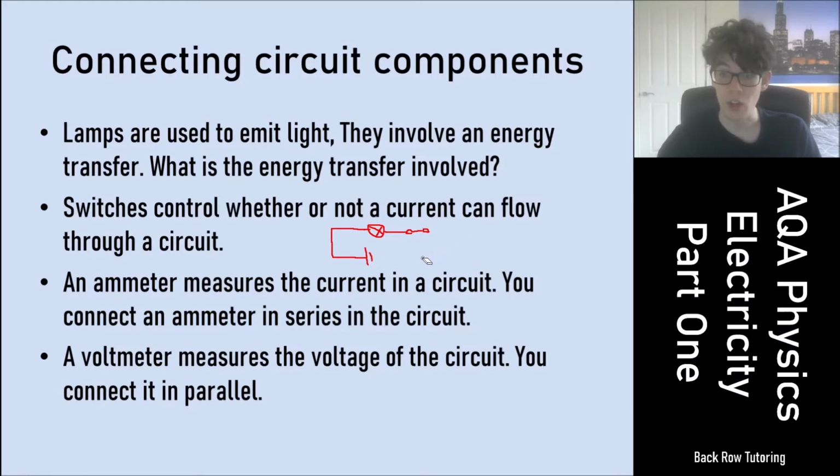would open the circuit up, draw in your ammeter into the circuit, and make sure that the ammeter is connected in the same loop, in the same wire sort of setup as the other things in the circuit. That's in series, so there's lots and lots of things on the same loop. Like a series of episodes, there's lots and lots of episodes. In a series circuit, there's lots and lots of components in the same loop.